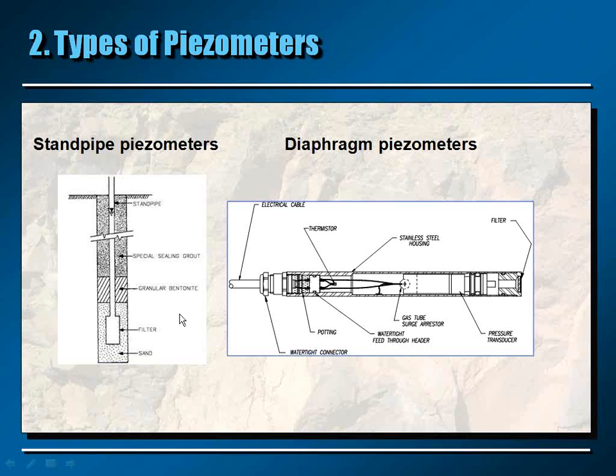You need a larger flow of water in order to measure a variation of pressure, because you have to fill this pipe. So in clayey soil, for instance, this can take quite a long time. We can have to wait for hours or days before seeing any change in pressure that will result in a change in elevation in the pipe of the standpipe piezometer.